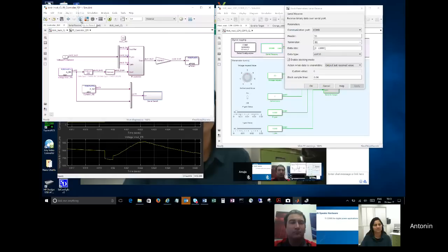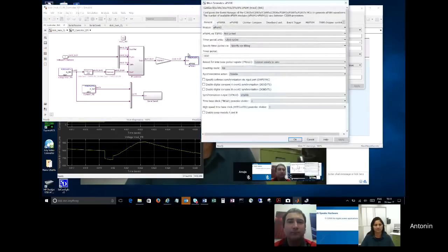So as in many C2000 applications, we want ADC to be out of sync with PWM. You don't want to convert while your PWM is transitioning. That's to ensure that your conversion is clean. So if I look inside this PWM block, you will see, first, that the PWM period is set to 1,000 clock cycles. I don't have any divider here on this PWM module, so the PWM counter runs at the CPU frequency, which is 200 megahertz. So 1,000 counts gives 200 kilohertz, and that's 5 microseconds. So that's the PWM period.